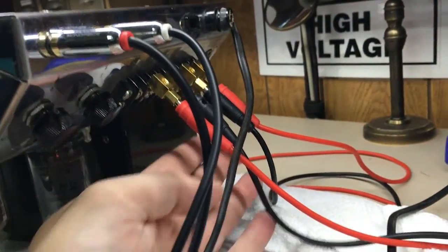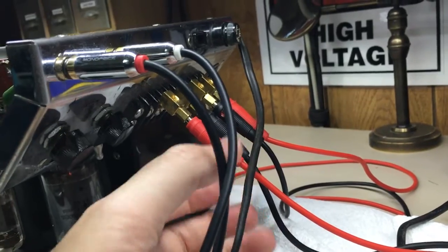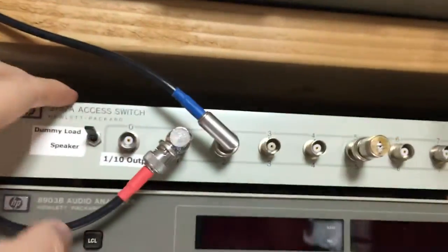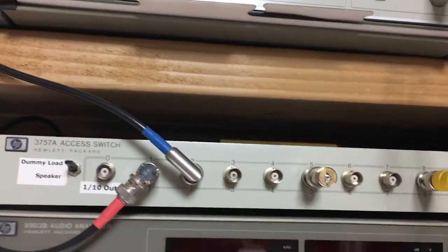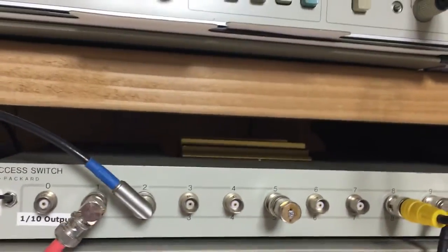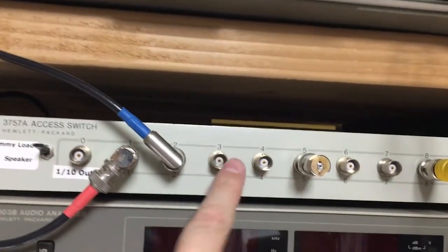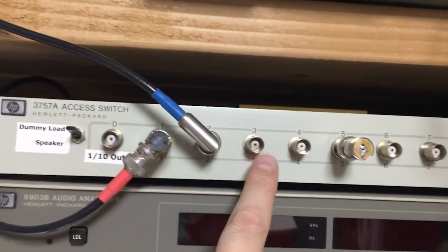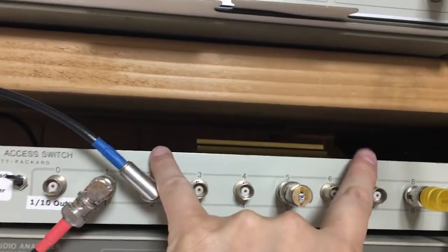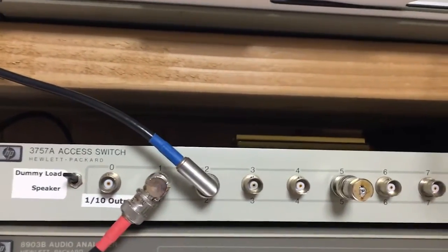Kind of coming out the other side of the Macintosh amplifier right here with these banana jacks. They feed up and into this dummy load setup right here. So two Dell 250 watt 8 ohm resistors. You can see them mounted up in there. And then paralleled across those are these outputs right here. So basically if you connect something up to this device, you're measuring across that resistance right there.